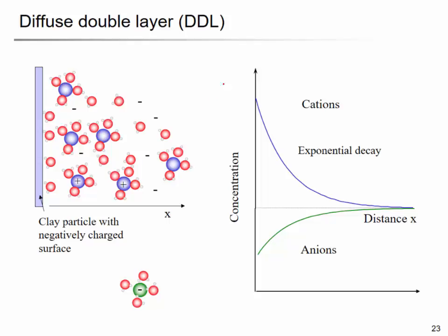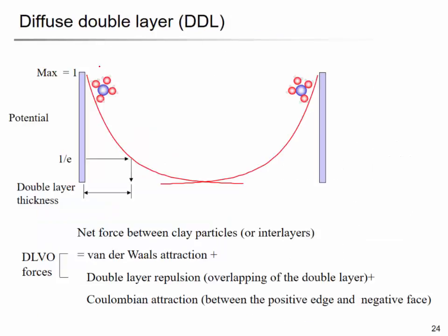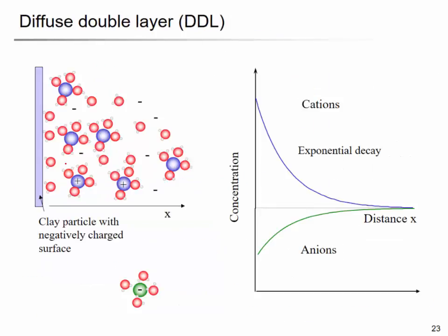So when you have dry clay, you always have a cation adsorbed on the clay particles. Right? So this is an electrically neutralized clay particle. The clay particle itself will have the negative charge. And because of the negative charge, it has a cation, and when you add water, this cation will be hydrated, and there's some water layer that is kind of structured.